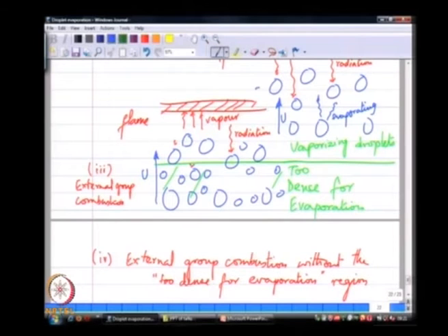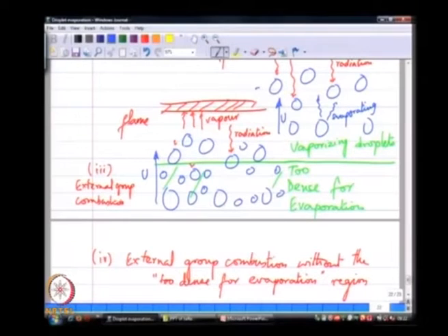And so, we are not really looking at a green line in a spray where below which there is no evaporation and above which there is evaporation; it is sort of a schematic for us to understand how this process happens. So, you could have a region very close to the nozzle where the droplet number density is so high that the ambient interstitial air is completely saturated at that given temperature, and heat is not being transported to that zone because, let us say, radiation essentially is obscured by the drops that are in between the flame and this dense spray region, or through some other process. Essentially you have a region where there is almost no evaporation, followed by a spatial region where you do have droplets evaporating and supplying fuel to the flame.